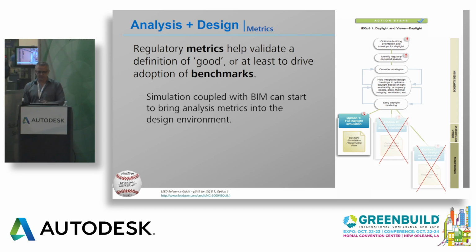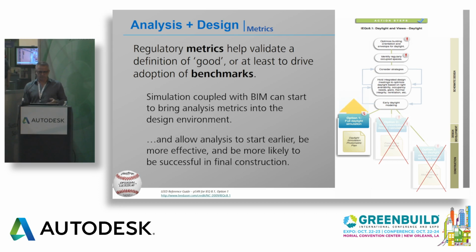You can see on the right-hand side the different phases of construction. We're seeing that we can actually pull daylighting analysis all the way back towards conceptual design. As soon as you've got a Revit model that's built with detailed geometry, you can start doing daylighting analysis. And since that information is coupled with the BIM model, those analysis results are going to be part of the design process all the way through construction documents.